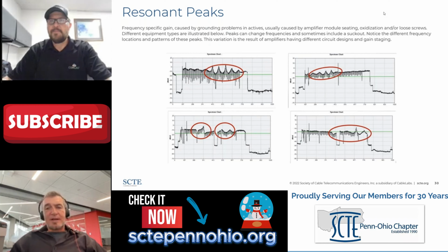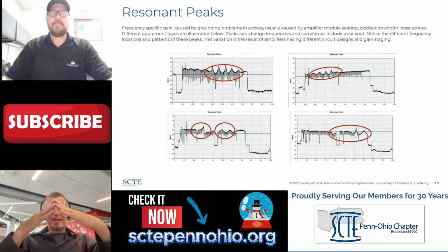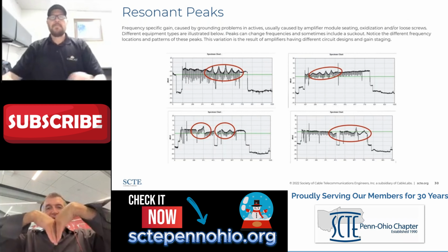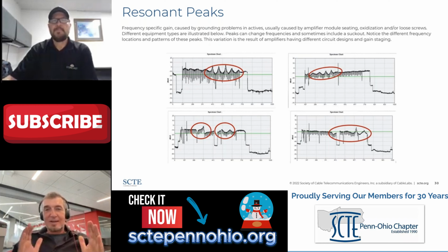But the corrosion on the amplifier module will cause an oscillation within the circuits within the gain stages and result in these types of peaks. And remind yourself when you see a peak, a null is one thing, that's actually attenuation. A peak is additive. There's an additional gain component. So think peak, amplifier, and you'll be on the way to getting to that problem.